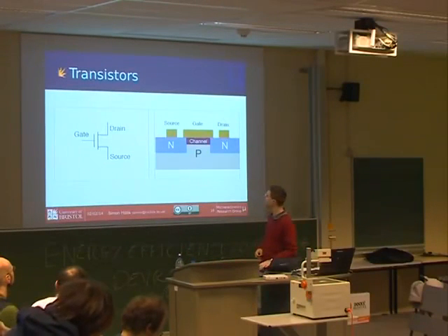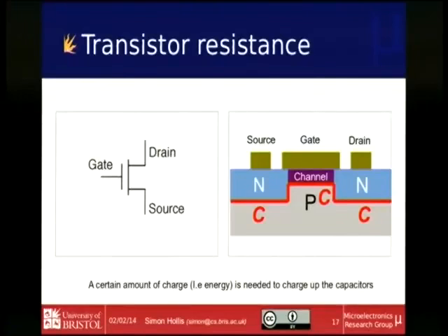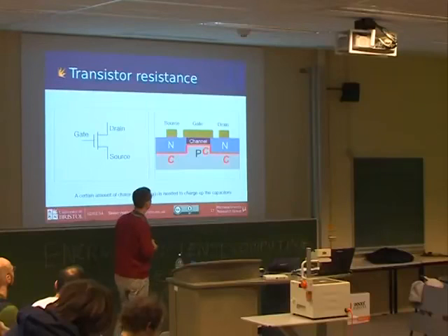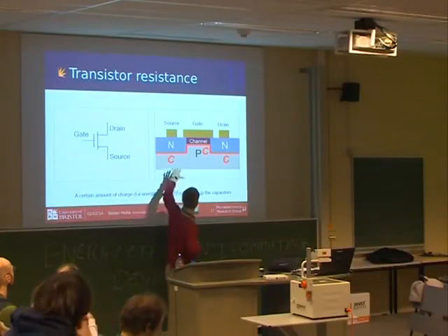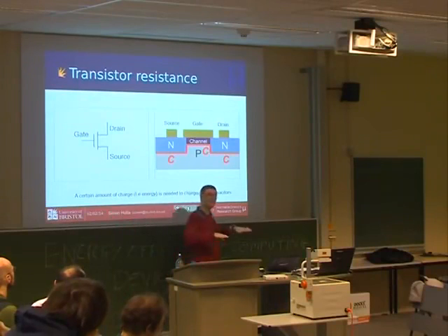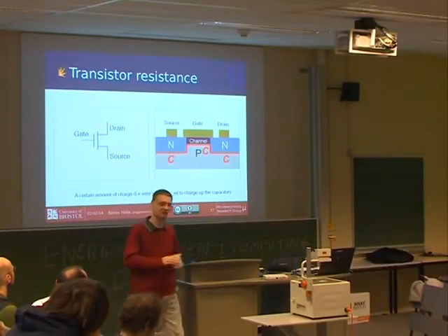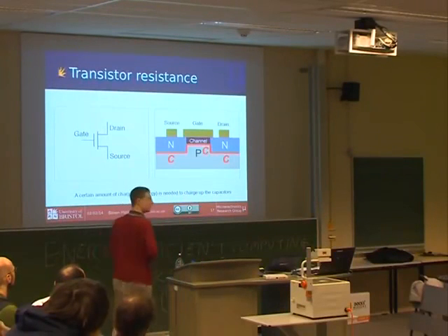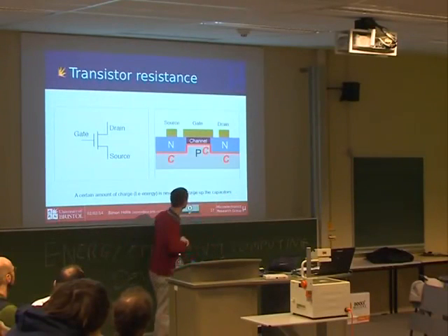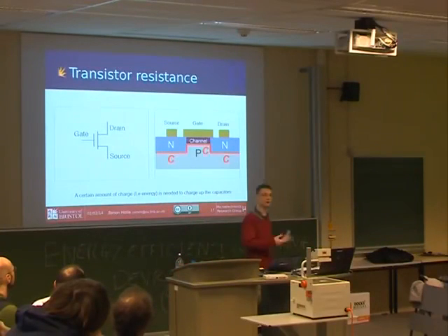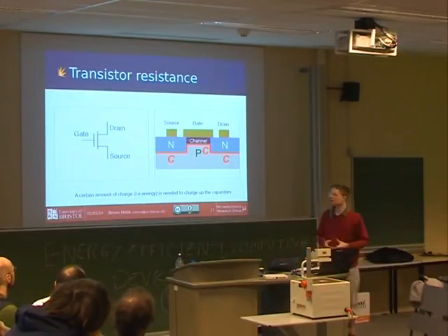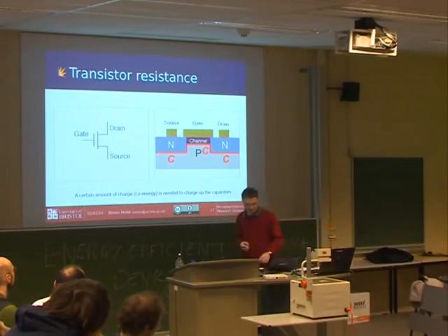Why? Well, the first thing is, we've got two materials separated together. This is a lovely parallel structure. That's how our industry has done so well, making these big, mass-produced, very flat devices. So I've got a big parallel structure, so what I've built myself is a parallel plate capacitor. And it's about as long as a transistor. So if I change the voltages at any point in the circuit, I actually start charging and discharging the capacitance of that part of the circuit. So that means that I have to do some work.